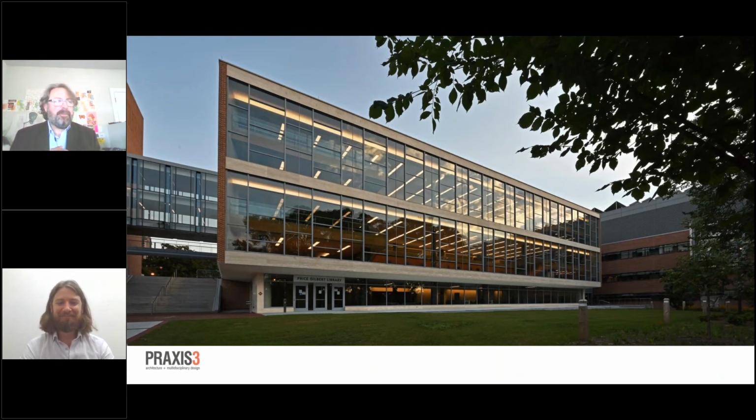In the 90s, this curtain wall was replaced with a 90s era curtain wall system, a sort of traditional Kawneer type 1600 curtain wall system with insulating glass, which performed better, but architecturally speaking, it did not have the subtlety that the original design had. It didn't have any hierarchy between the width of verticals and horizontals. And there were some subtle things that really didn't do service to the original design, the 1953 design of the building. And some of the IG units had become cloudy.